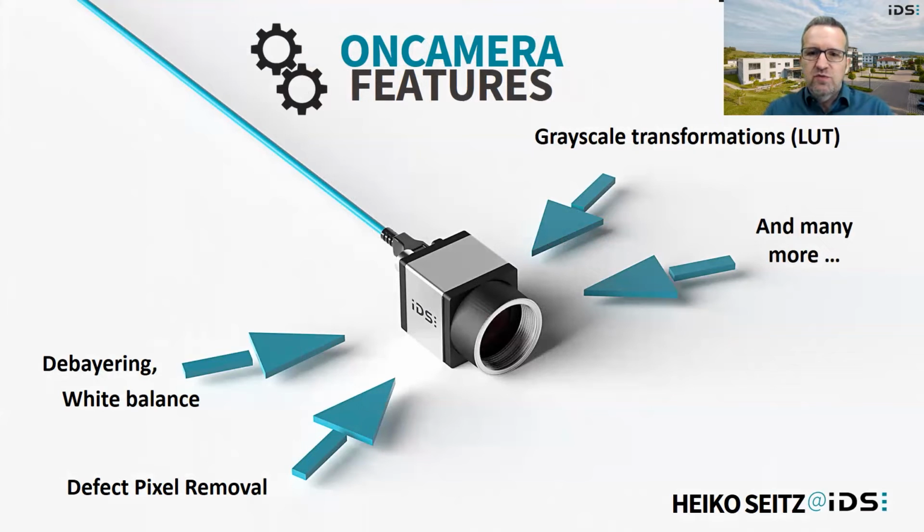However, in order to perform these pixel operations with a high performance in the so-called pixel pipeline of the camera, special hardware components such as FPGAs are required. Apart from increased energy consumption and thus higher heat generation due to the additional processes that now run in the camera, each additional function code also requires more space in the FPGA of the camera.